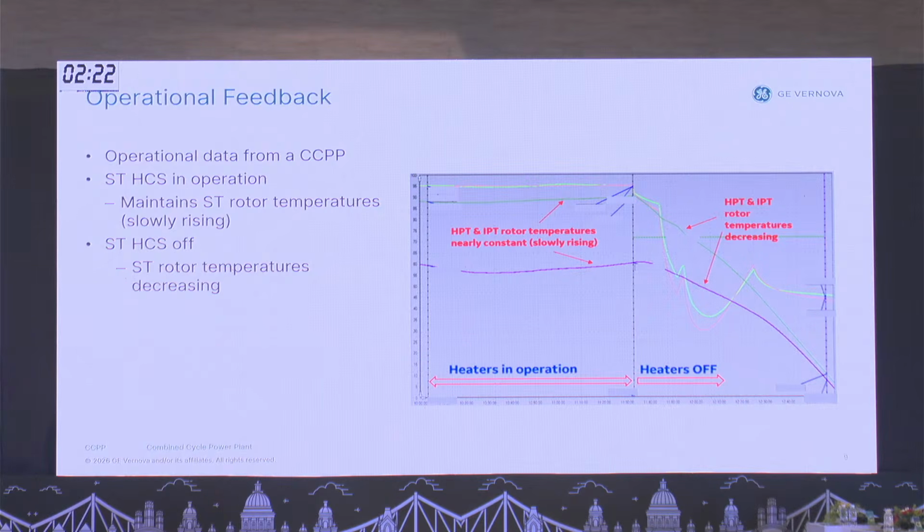Today, we are working on one of our own steam turbines in NTPC Solapur Super Thermal Power Plant. There we have started studying one unit, because before installing such a steam turbine heat conservation system, you need to do some stress analysis and finite element study, to find what temperature is really suitable to maintain for a steam turbine. It should not be so high that it is getting undue stress, and it should not be so low that you are not actually getting the benefit of warm start.